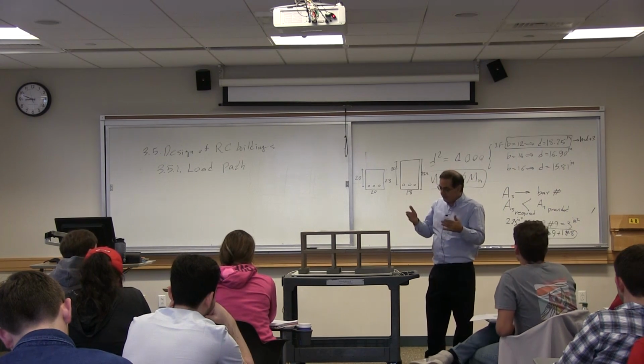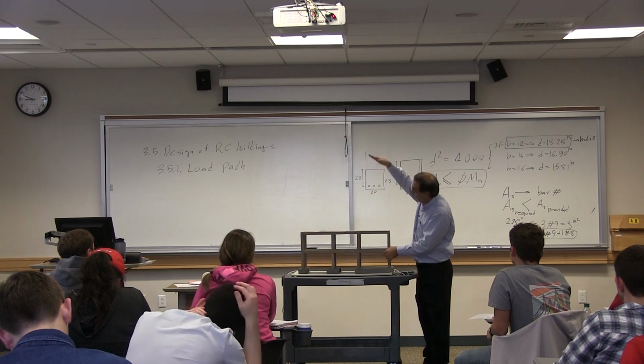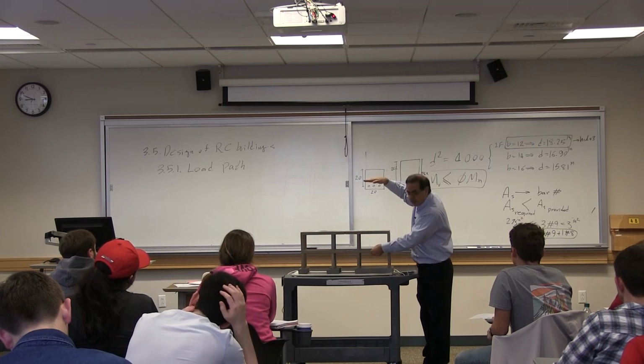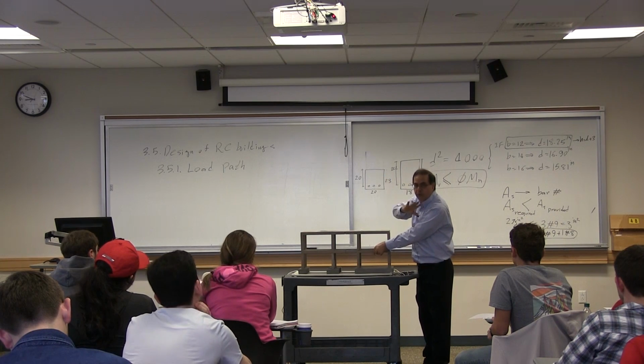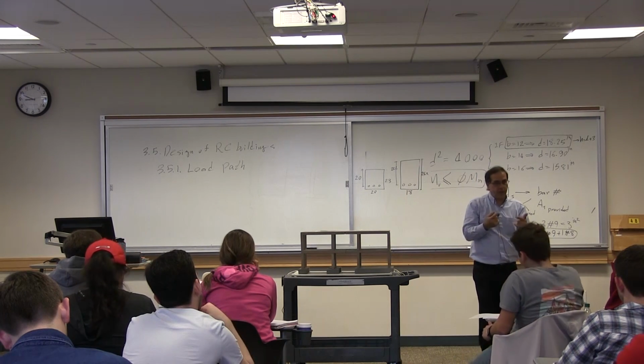I have seen some students have this misunderstanding that if it's taller, the load of those beams would transfer to this beam. The answer is no, it will not transfer to the beam. It would transfer to the column. Why? Due to the load path.